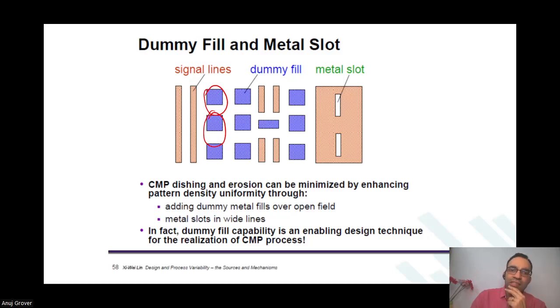Yeah, see, you designed your IO region, for example, and you extracted that. You did all your verifications with that IO. Is it not? You said, okay, this IO will be repeated 10 times, 20 times, 50 times, depending on number of bits. You estimated the RC of the signal, and then you would do verifications. Then you would characterize setup time, hold time, everything.